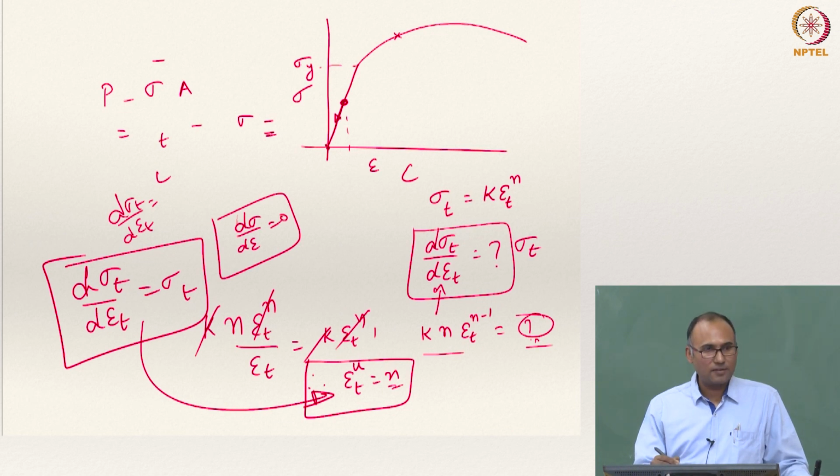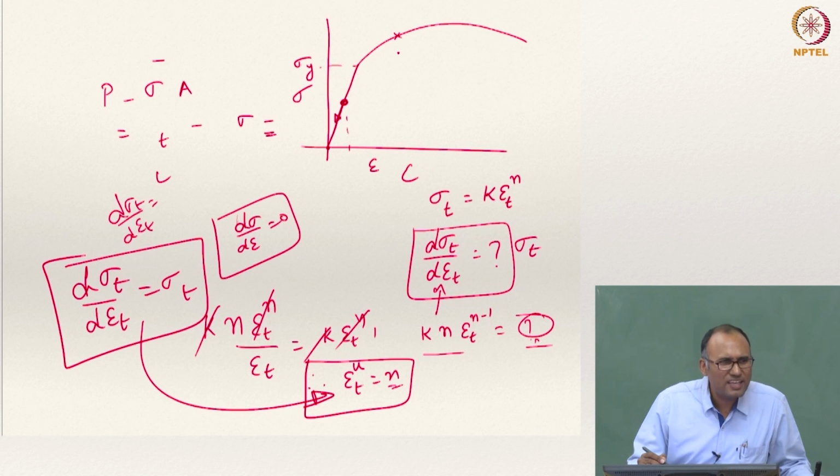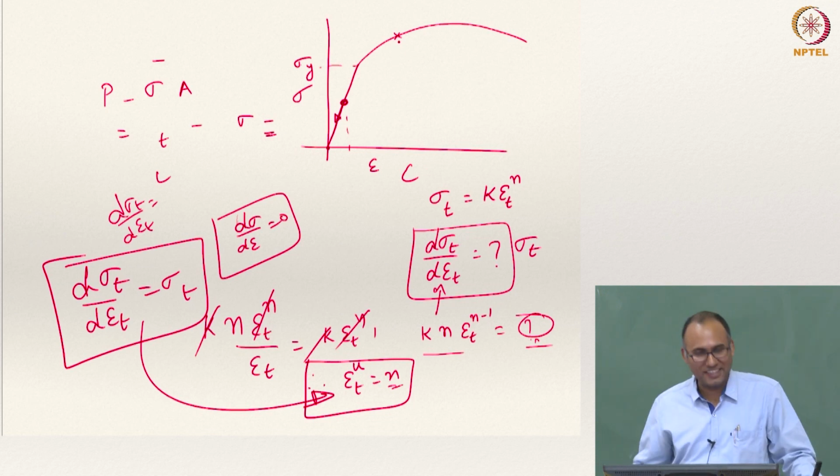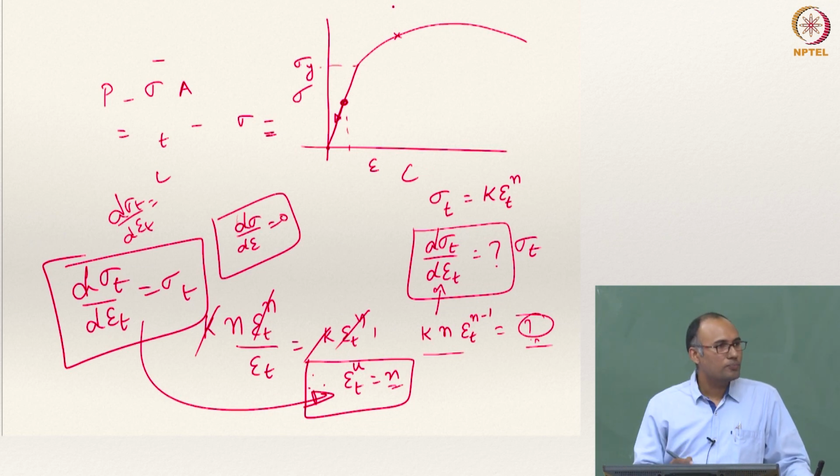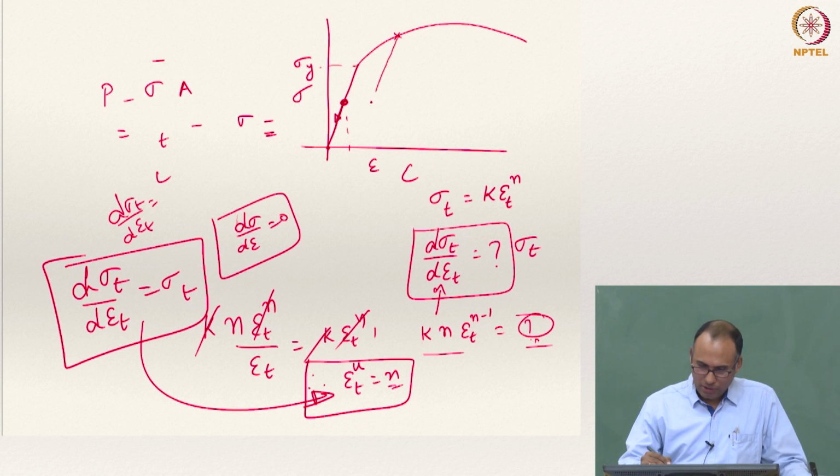This region, this line. Okay. What did you say? Hooke's region. Okay. So you will unload along a line whose slope is equal to your elastic line. Why is that? Why should it be parallel to that line? You said you have to unload like that, right? These two should be parallel. Why should it only unload along that line?